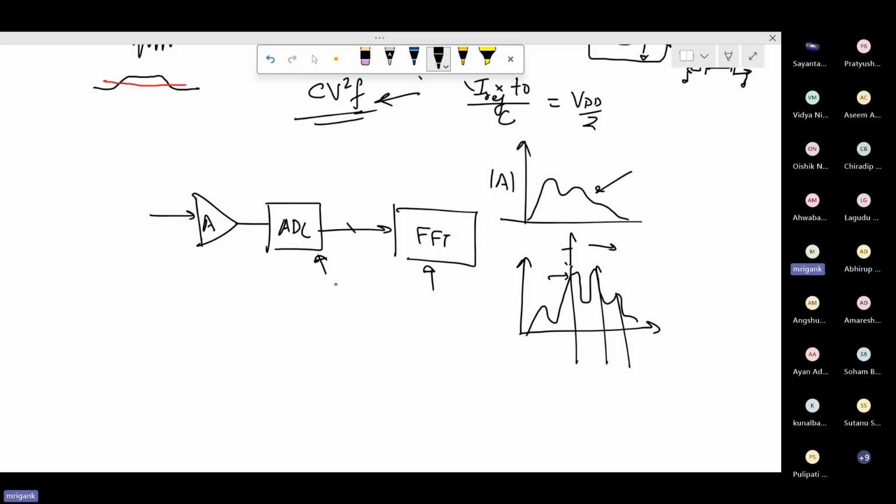So again, a signal processing person may tell you that this approach of digitizing the data, then doing a frequency transform and looking at the frequency spectrum, at which frequencies the peak is coming and which frequency content is changing, and then applying detection based on that, will first of all be less sensitive to changes in signal amplitude. Depending on the sensor, signal amplitude may change. Some sensors will give you a higher signal, some a lower signal, and then you have to adjust the gain of the amplifier, etc.